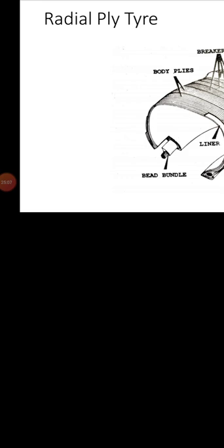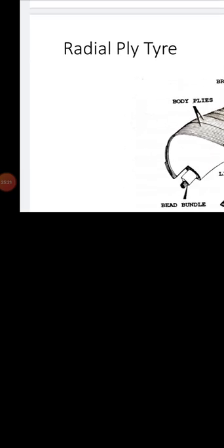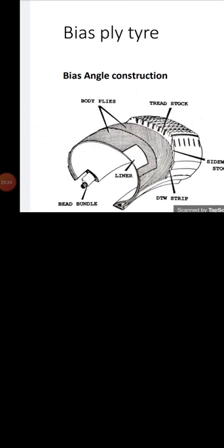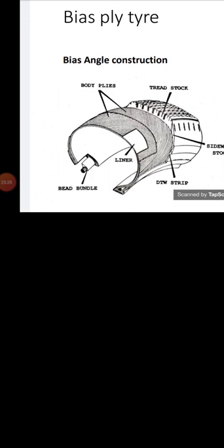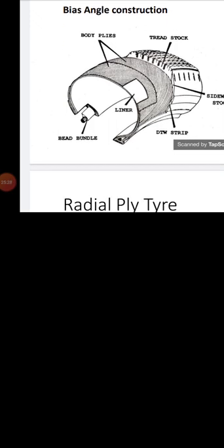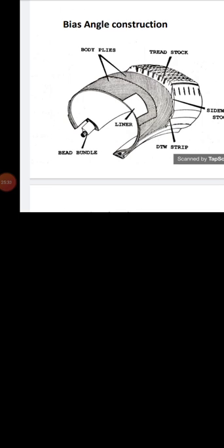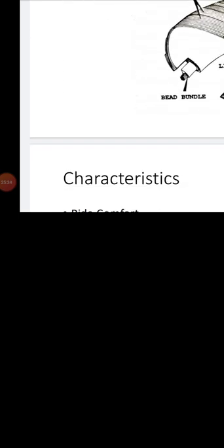And the greatest difference in tires lies in the cord materials and the way they are put into the tire, the cross bias cord angle. In case of bias angle construction, that is near about 30 to 40 degrees, this provides the cross side to side walls also.